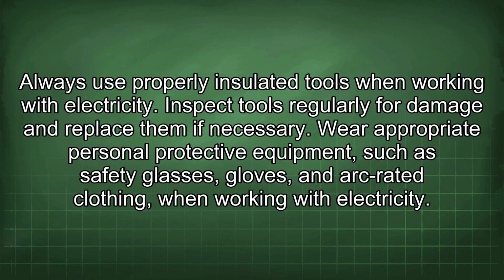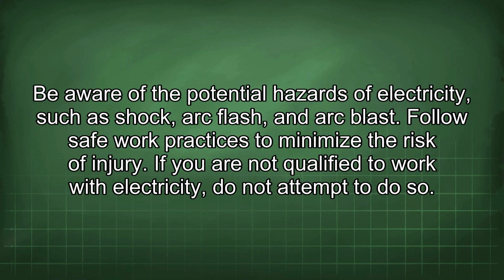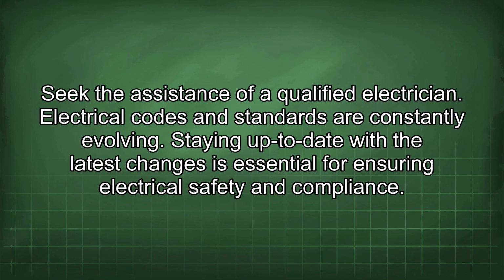Wear appropriate personal protective equipment such as safety glasses, gloves, and arc-rated clothing when working with electricity. Be aware of the potential hazards of electricity such as shock, arc flash, and arc blast. Follow safe work practices to minimize the risk of injury. If you are not qualified to work with electricity, do not attempt to do so. Seek the assistance of a qualified electrician.